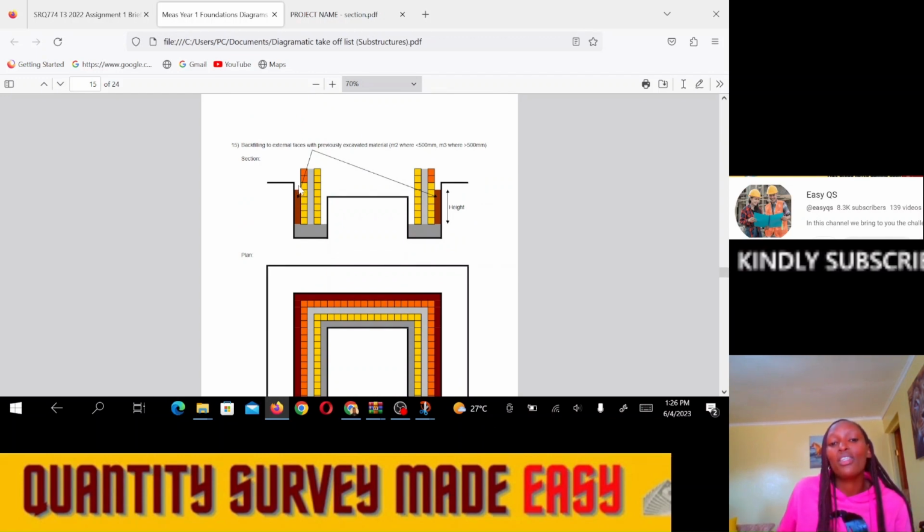We shall reinstate some topsoil from the stripped level upward, because maybe we need to do some beautiful plants around the house. But in case we need to do paving, maybe we could replace it with the rest of the soil. So first of all, we usually measure it up to the stripped level before we decide what we shall reinstate where we had removed the topsoil.